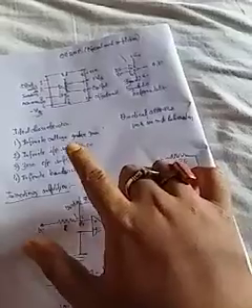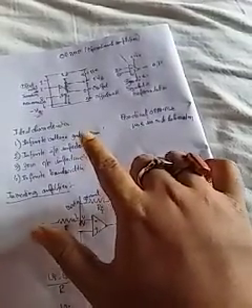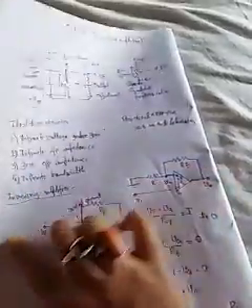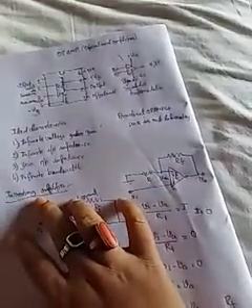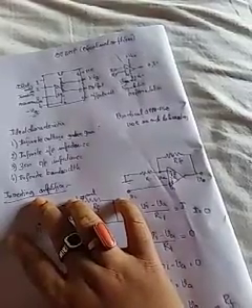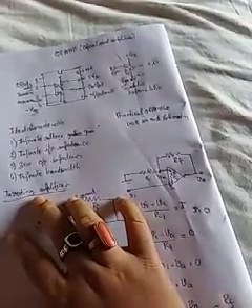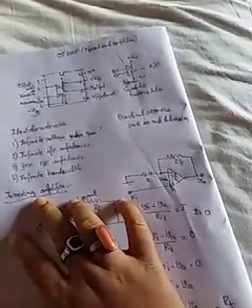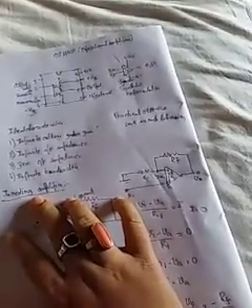It means if the ideal voltage gain is infinite, it will be a high voltage gain for a practical op-amp. Infinite input impedance in the ideal case means the input impedance is very high, and the output impedance is very low in the case of the practical op-amp we use, that is 741C.